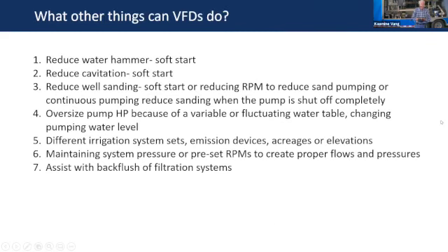So what can they do? There are a lot of things we're going to demonstrate here that they can do, and I may have to come back to this list if I've forgotten something. First is a soft start. They'll wind up the pump slowly. Usually when you start a pump across the line, you just hit the switch, and in a split second it's full speed, and it takes a very large inrush of current off the transformer.